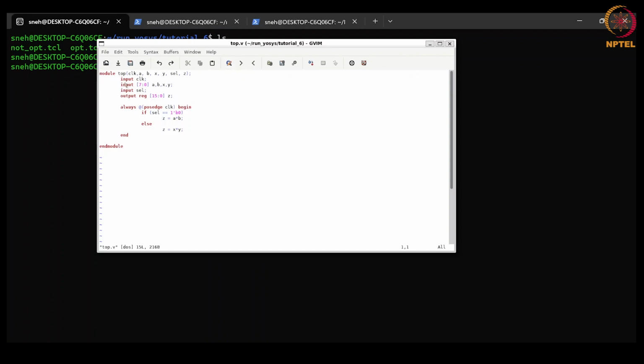If we look into this Verilog code, we have a top module whose name is top, and this Verilog file has only one module. Within this always block we have the RTL construct that we talked about. We expect that the tool will implement this circuit optimally by using only one multiplier.